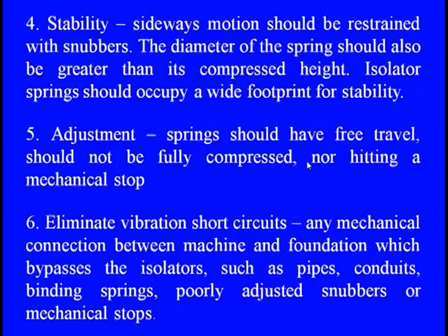Stability is a real cause here, because if we provide an inappropriate spring with the isolator, certainly unstable features will appear in the machine. It sits between the solid foundation and the machine, and the machine lies on this spring. So when they are generating oscillation and the springs are not leveled properly, certainly instability will come to the machine base.